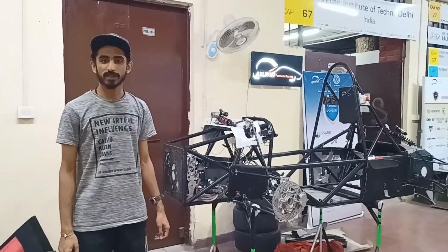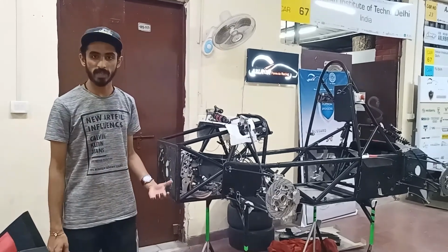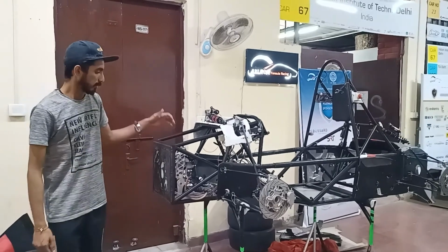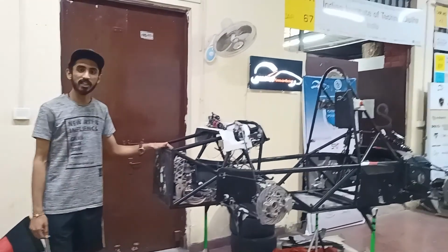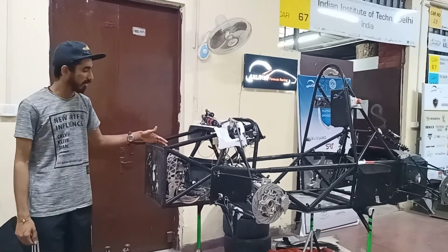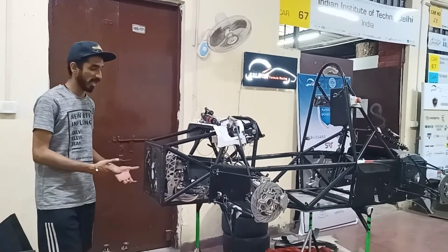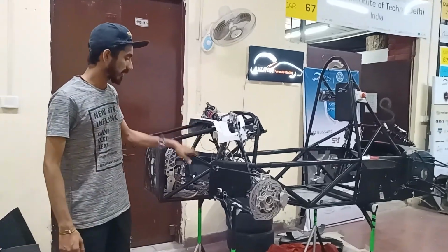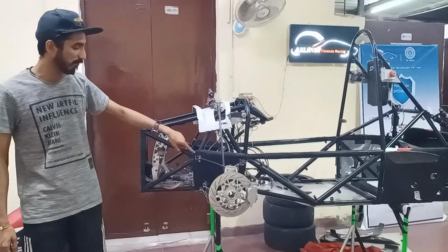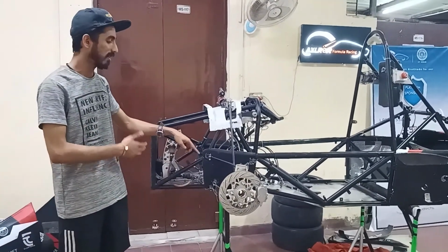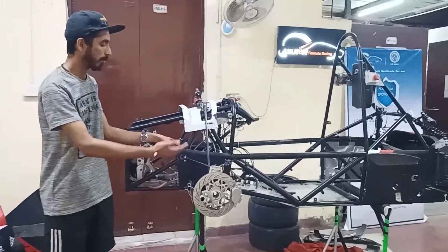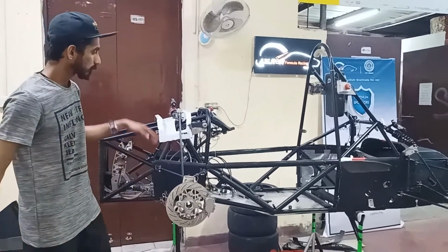Hello, in this part of the presentation, I'll be showing you the space frame chassis which we built for our Formula Electric race car. This chassis is made up of carbon steel tubes welded together to form the structure. This is called the front bulkhead, where the impact attenuator is attached. These are all the chassis members. This is the node location where we prefer to give suspension points, as wheel loads coming from the wheel or road surface will be applicable to these points.